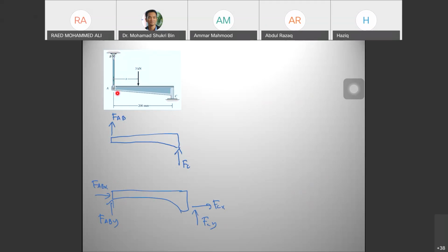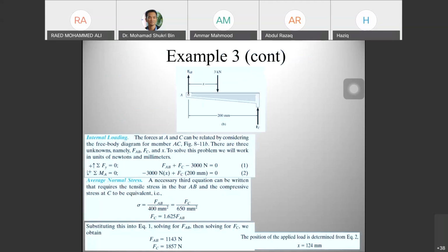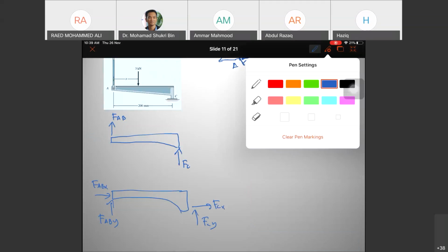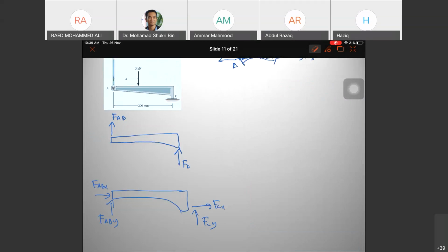Although this is spin, but this is a two force member, you know the direction of a two force member is only one direction, along the line of action, alright? So let's say you have this one, right? A and B. Two force member only acts in this one, FAB and FAB, alright? Force at 2 points, right? Okay. So that is your FBD.